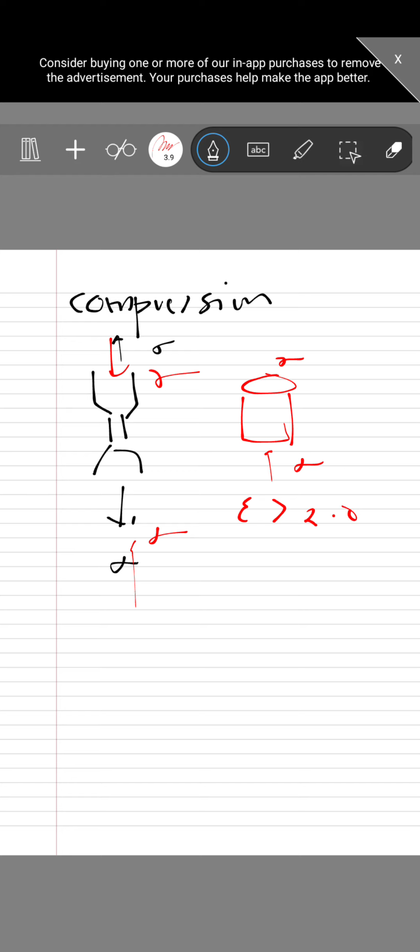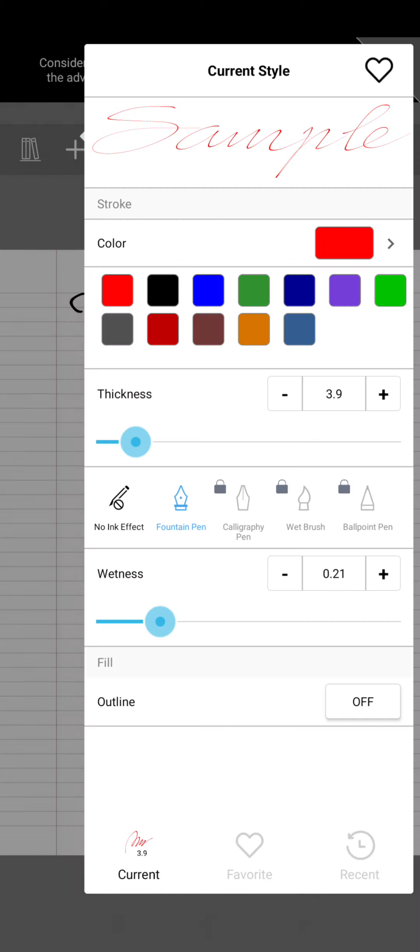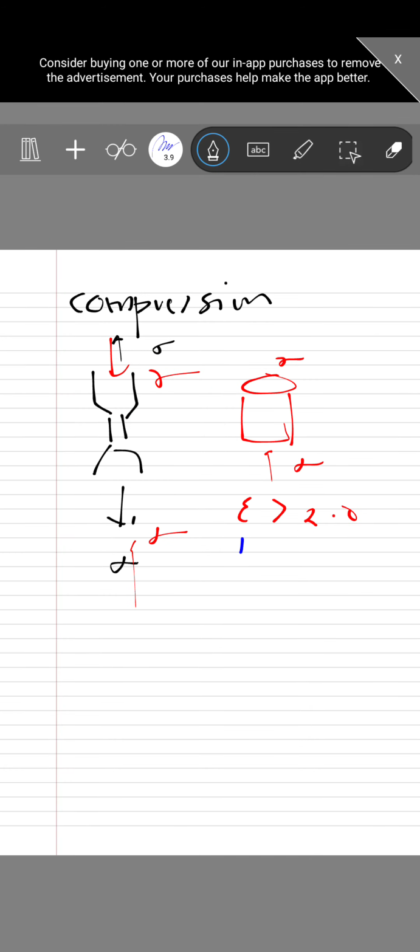There is no problem of necking involved, provided the material is ductile, that means it is a metal. A strain of 2.0 means it has reduced to half of its initial dimension.